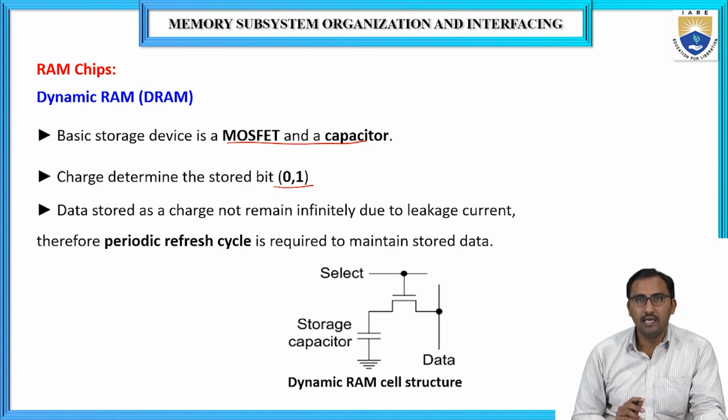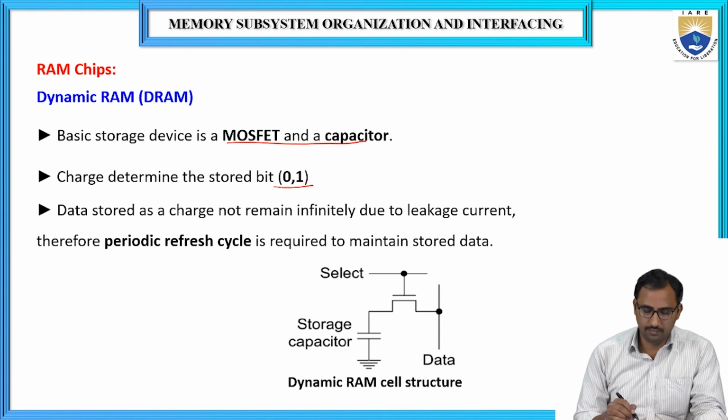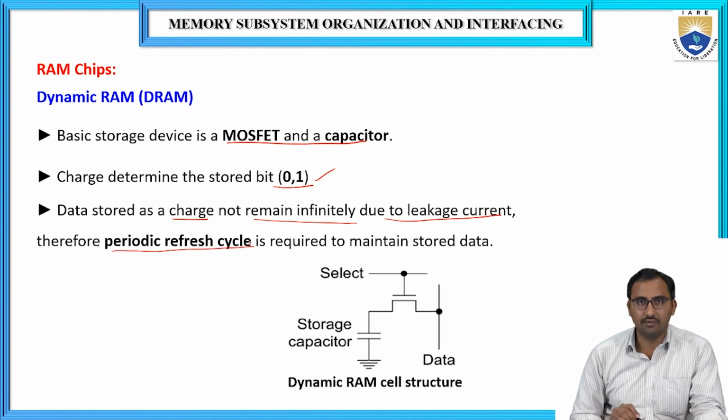That means if the storage capacitor is fully charged, then it will be considered as a logic 1. And if the storage capacitor is completely discharged, then it can be considered as a logic 0. And the data stored as a charge cannot remain indefinitely. Due to the leakage current, periodic refresh cycles are required in order to maintain the stored data.